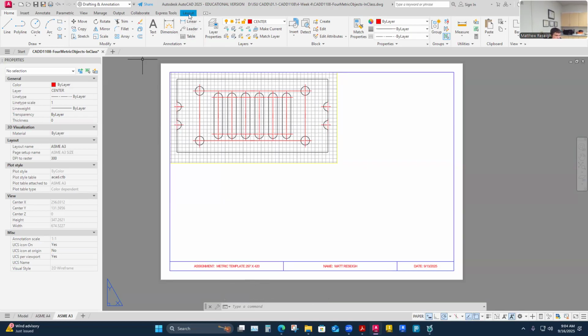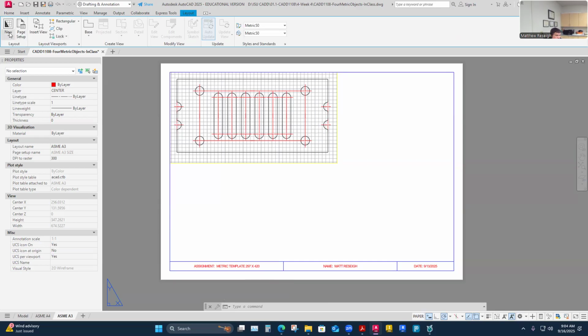If you click this, which I don't think we've used yet, this is where you add a lot of different things. But the one thing I want to point out is the rectangle, this layout and viewports right here. Usually a viewport is just a rectangle, but we can make different shapes as well, like polygon. I use rectangle probably the most, maybe because it has that little star on it and it catches my eye. That's exactly what our viewport was here, a rectangle viewport. I've got four objects to put on here, so I can plan on four different spaces.